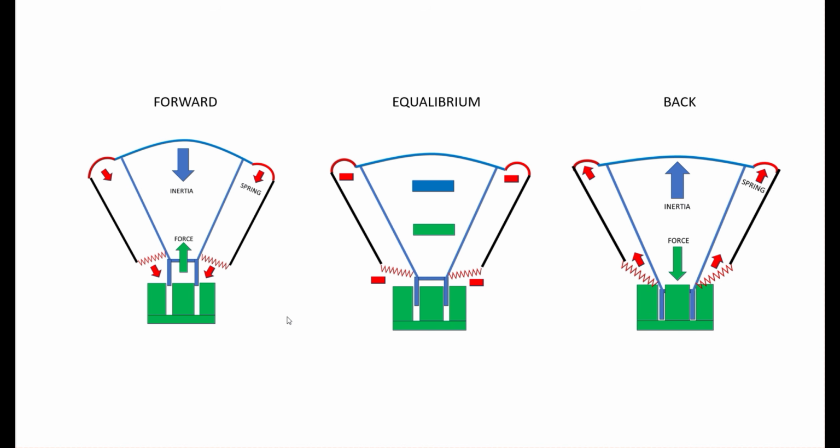Because if you think about it, let's say we have really stiff springs, right? What that means is that it's going to be harder for the motor driver to push the cone. The springs are going to be pulling very hard on the cone. That means it won't extend, or the excursion of the cone will be less. And when the spring starts pulling on the cone, it's going to pull it back to the resting position very quickly, right?